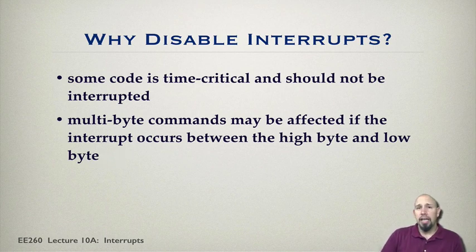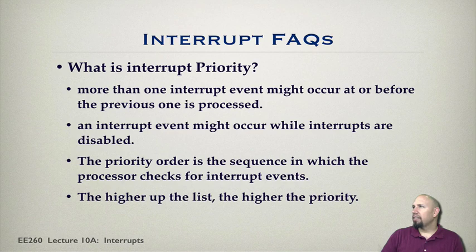Also, it's very common to disable the interrupts when you're in an interrupt. That prevents your interrupt from being interrupted by a higher priority interrupt. So that's important. Interrupt flags.